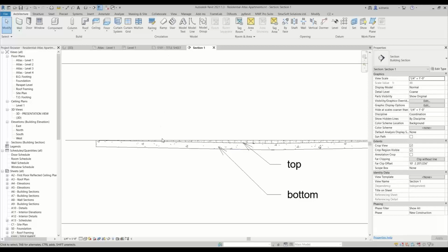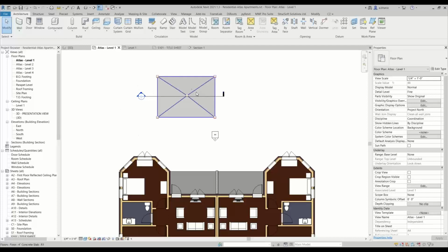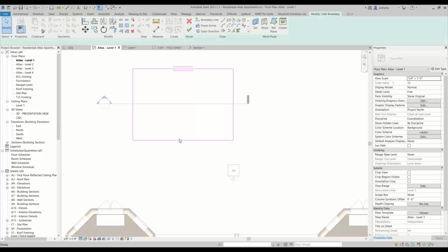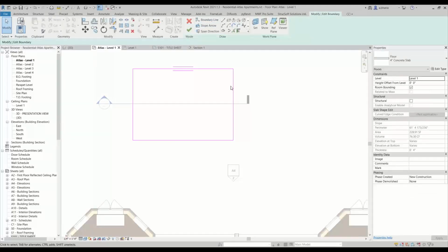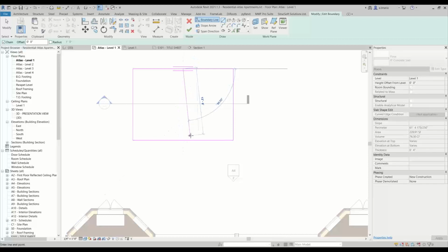or your ceiling. And that would be because your joists won't actually place like this, right? So if your span of your joists is this direction, you can't really have them bend down here and then go back up, right? You'll probably split up the panel in the middle here. So you would probably need to set up, you would want to set up your panels separately like that as well. So you might actually want to come here and be like, actually my boundary, I'm going to just copy this. Actually, my boundary line is in the middle here, right?